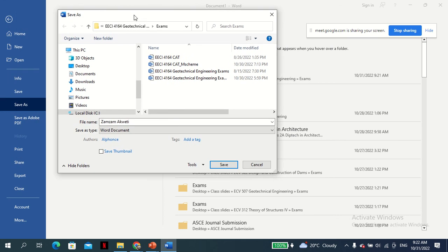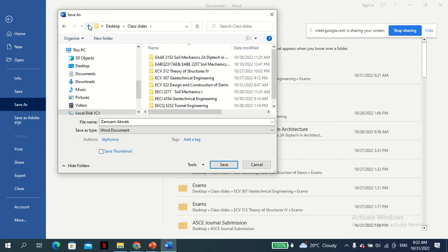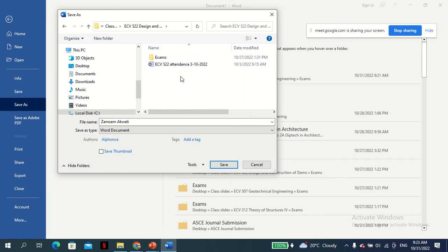So when the water is under extreme high pressure, you need to provide a way that it can flow away. Otherwise, if you don't let the pore water pressure go down, the next thing is it will destroy the embankment. So you need to provide a stopgap such that as soon as the excess pore water pressure increases, it's able to dissipate and then restore stability. Is that clear?